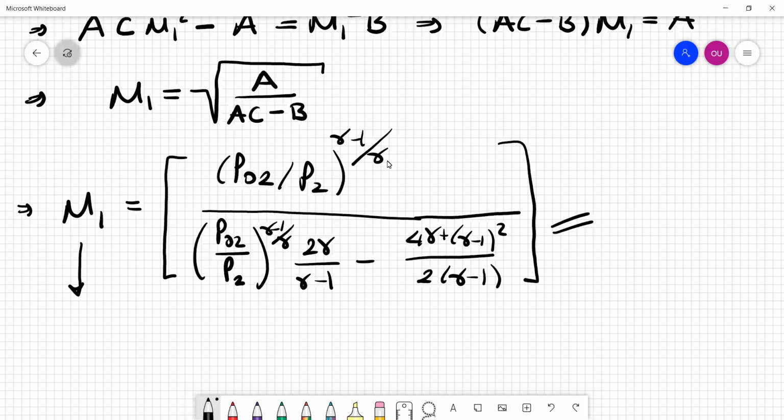Mach number right in front of the shock wave, just ahead of the pitot static tube at the nose of your aircraft, but the flight Mach number will be very close to that, okay? Very close to that. So since the flow is uniform ahead of the shock, a normal shock wave, we can safely say that this is true. So ahead of the shock wave, this will be your flight Mach number.